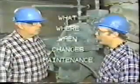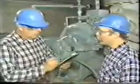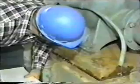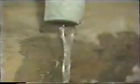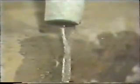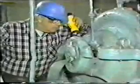The answer to the last question Gene asked was that the packing had been changed not long ago. Gene is going to go right to work with his operational check. The runoff on the outboard packing seems quite heavy, just as the operator has indicated. Although the fluid in this pump is water, other pump fluids may require special safety precautions. Be sure to follow your facility safety precautions when checking runoff. Check for the source of the excess leakage.